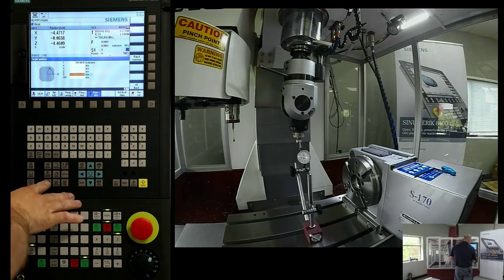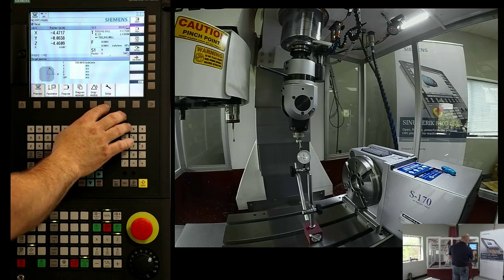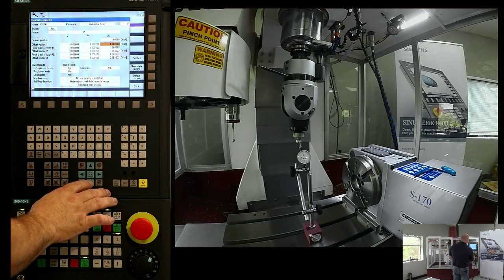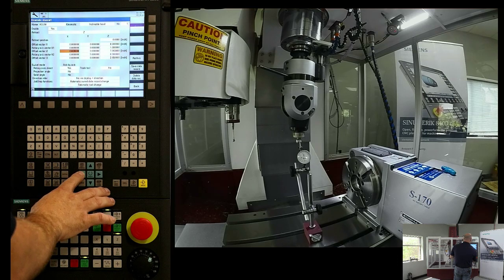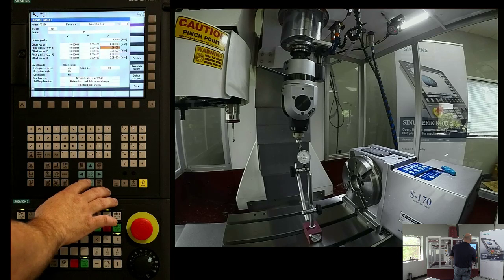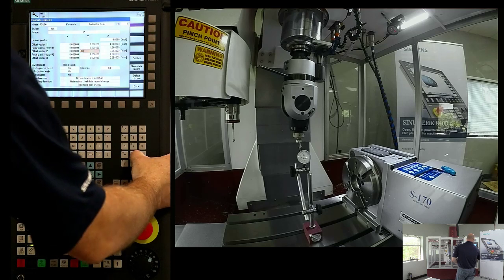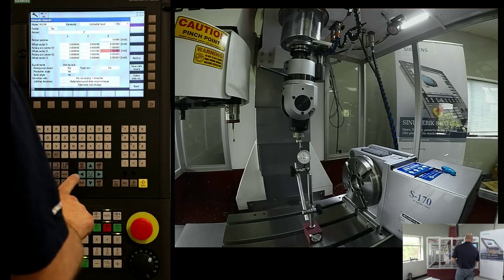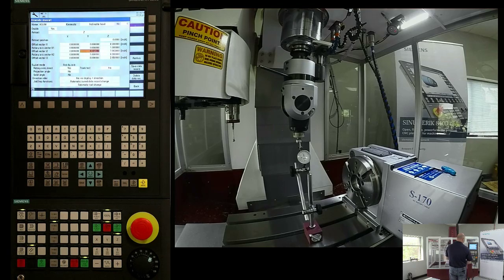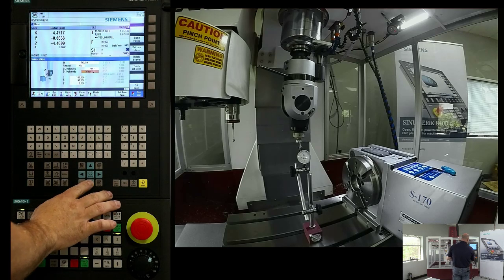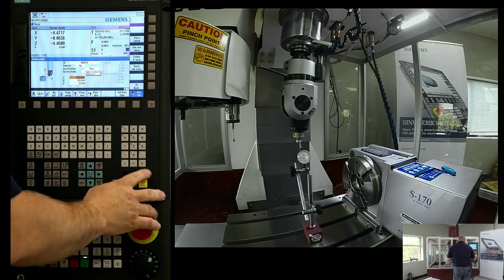Then what you're going to do is come back to the swivel data mask, and enter these values in the offset I2 vector, because I'm compensating for where the center of that rotary is. To give you an example, I'm going to plug in 0.001 here right now. Okay, so now when I come out, I want to set my swivel axes to 0 and 0. That's where I'm setting right now.